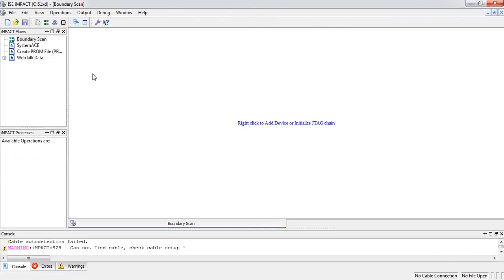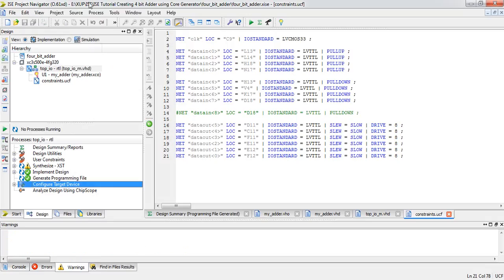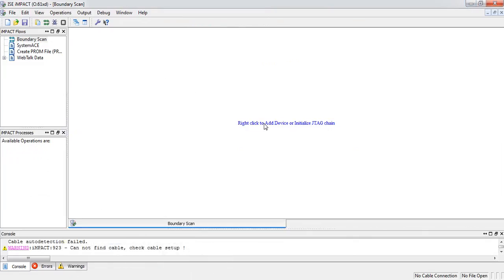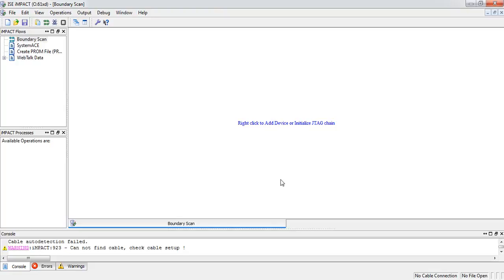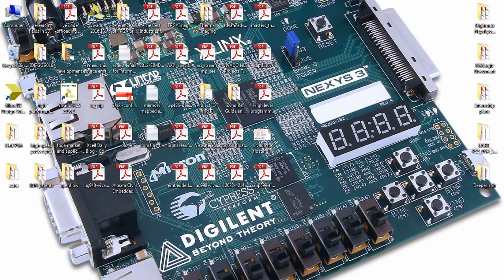Then we can select yes, and then we will locate the bit stream of the current project. Project is here in your directory, isn't it? Here. So after that we will click yes. Then we will click bypass for PROM and CPLD. Then we will do apply and OK. Then we will click on the first chip, which is the FPGA, and we will click program. If the programming succeeds, it will show up here. Then you can see your output in your Spartan 3 or any other board.